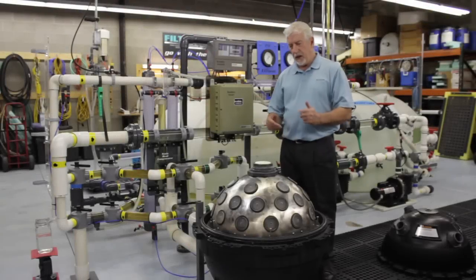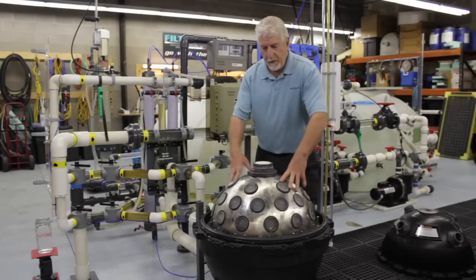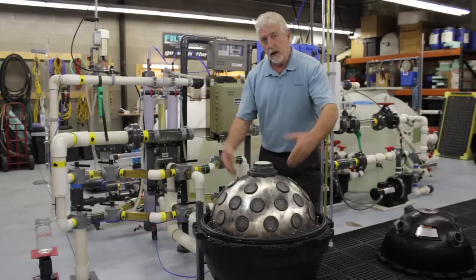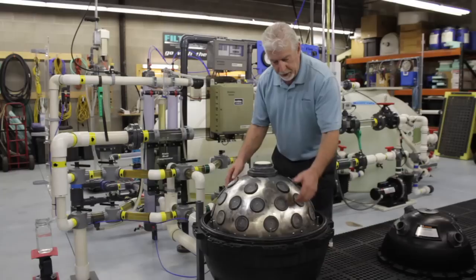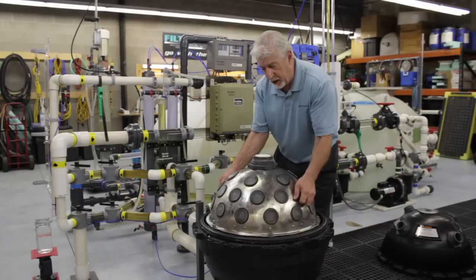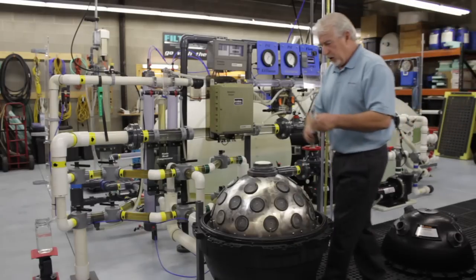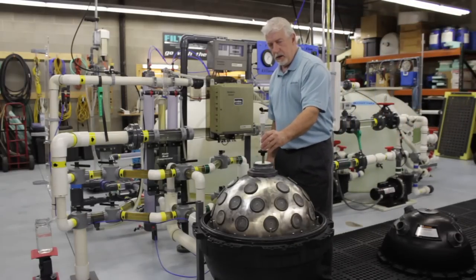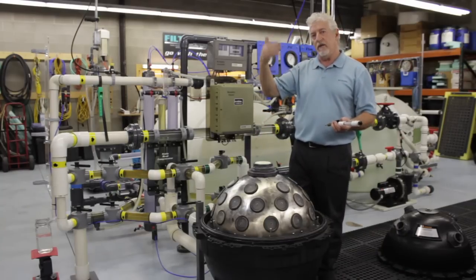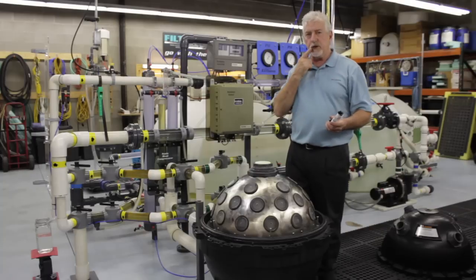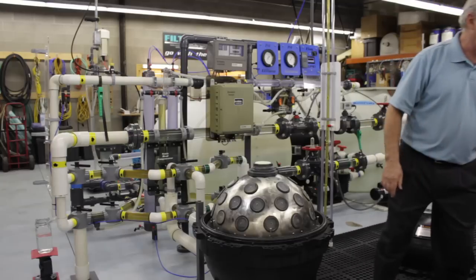Okay folks, now we're inside the radial flow filter. The media container is composed of 2 hemispheres that are connected together with the rubber bellow, and the rubber bellow keeps the granular media captivated within the sphere. And it can be down and compacted, or it can be up for backwash, and you watch that happen with the position indicator when I had it up and running. Down, up. These will be included on the production units to let you know a barometer of how the operation is going, and when you've had enough attrition to the media that you don't have enough compaction and need to replace it.